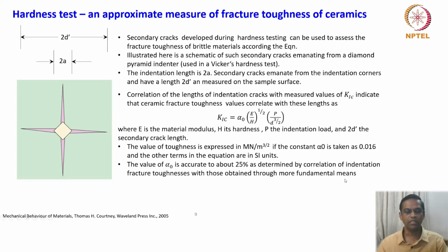You see, it is quite interesting, right? So I said that knowing the fracture toughness of ceramics is very important, and it's technologically also very important. So measuring the fracture toughness just by means of a hardness test is also very handy. Though it gives not a very accurate but an approximate value, nevertheless it gives an idea about the fracture toughness. Okay. So this is another interesting aspect of measuring hardness in ceramics.